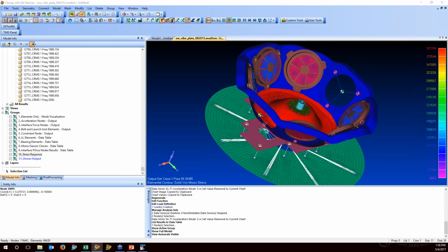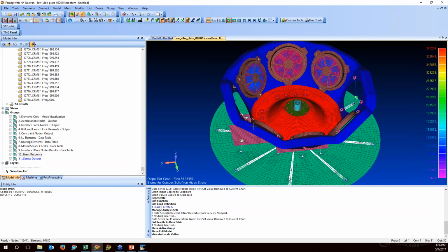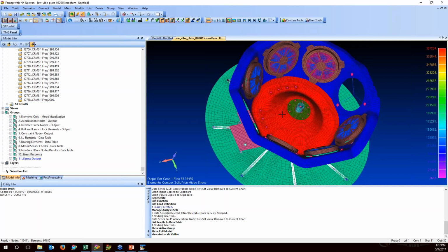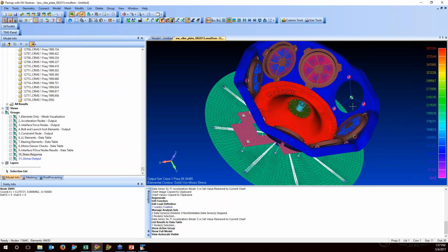Another question from Mark Anderson was about use of an RBE2. Now the RBE2 just uses a rigid point to spread to the constraint locations to drive to a center point. I actually do have RBE3s here in this frequency analysis, mainly for these mass elements. Again, that's mainly the difference between an RBE2 being a fully rigid element and an RBE3 being an interpolation element. And if you have more questions on that, definitely contact us for this.